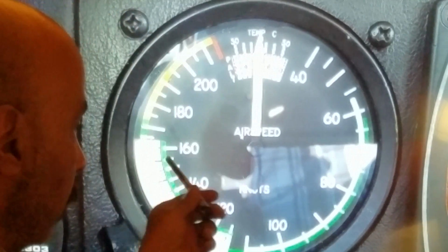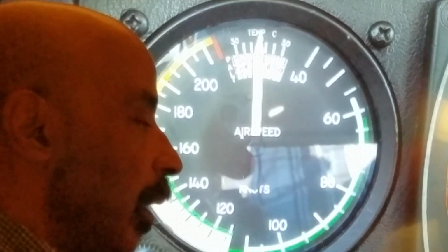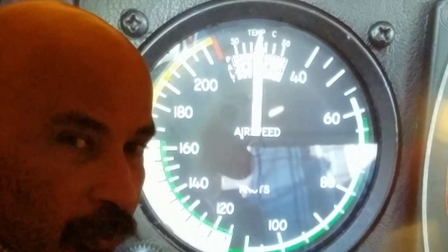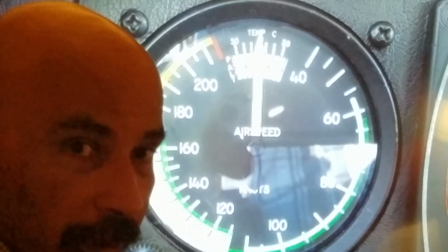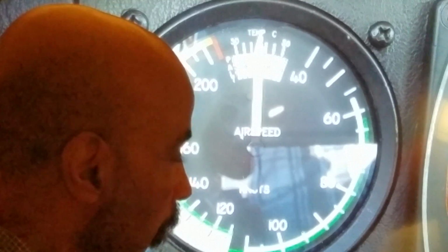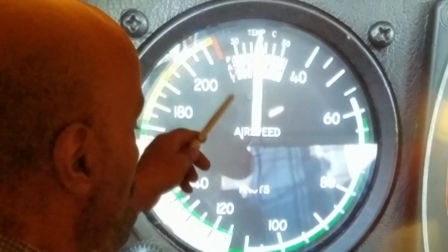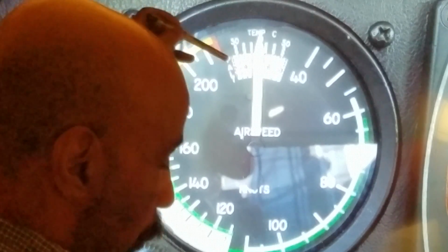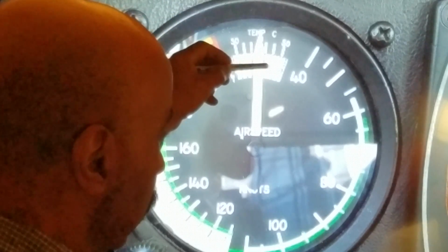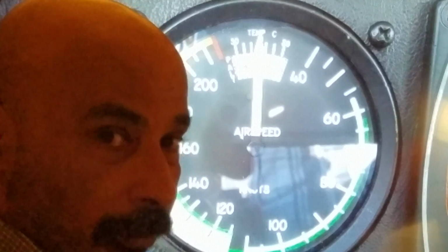Determining the true airspeed of this aircraft going through the air is not typically something that most pilots would really waste time to do. They're more concerned about the ground speed and fuel consumption and things like that. But true airspeed on this gauge can be determined by rotating the pressure altitude card to the actual pressure altitude, and that is determined typically by setting your altimeter, and we'll get to that later when we talk about the altimeter.